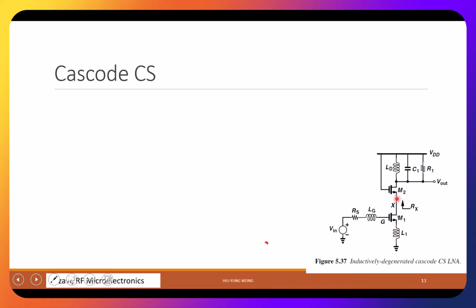We know that this can be treated as another transistor, another stage, right? You can say that I convert voltage to current, and now it's the current as the input to this. What type of amplifier is this? If just looking at this one, input is going in, common gate, right? Because the gate is at constant voltage, right? And then this is the output.